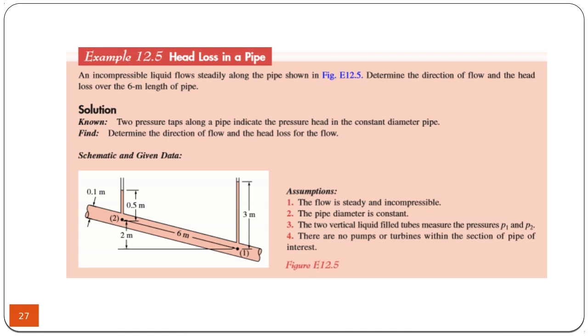An application of this energy equation. Why do we call it energy equation instead of Bernoulli's equation? Because in Bernoulli's equation, we assume that there is no friction, and there is no pump, there is no turbine. The difference between the energy equation and Bernoulli equation is the inclusion of losses plus pumps plus turbines. When you remove them, it becomes Bernoulli's equation.